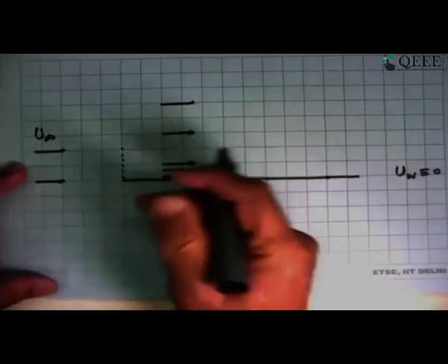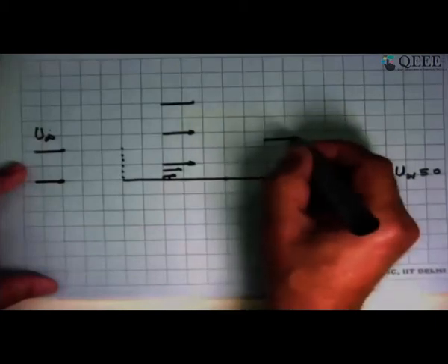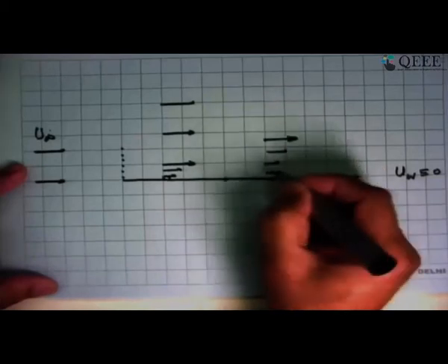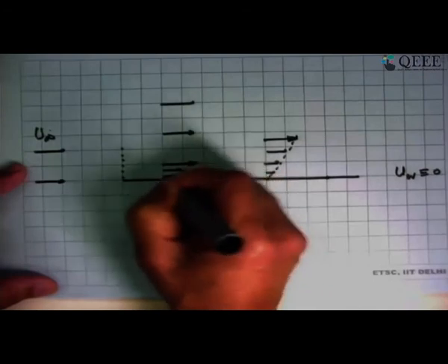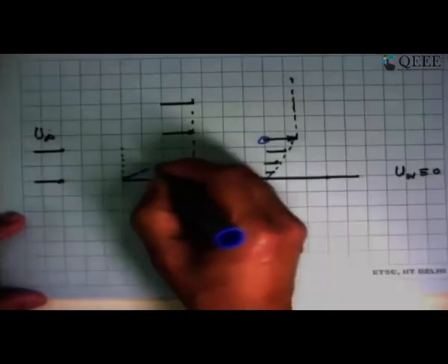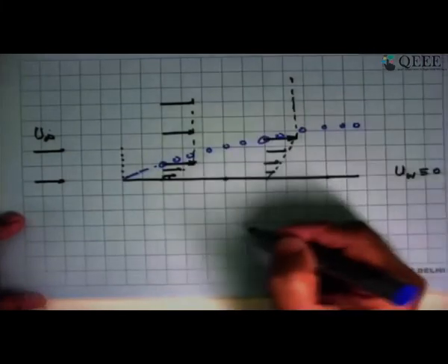Further down, the drag has now had its effect. It has slowed down elements further away from it. So you have an element here which has u infinity, and elements below this, they all have less velocity. So you got velocity profile like that. And then outside this, it is flat. That means there is a certain region, and we take these points where u infinity is there, we will get a locus of points where outside this the velocity is u infinity.